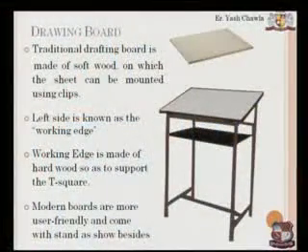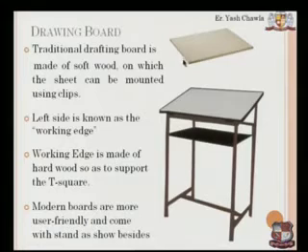That is where the drawing board comes in. I have a drawing board of soft wood, on which I can mount my drawing sheet with clips, just like we mount clips on clothes that we hang on the wires while we keep them for drawing. Well, the speciality of this particular drawing board that we use for engineering drawing is that it has a working edge on the left hand side. Now this working edge has a great deal of importance in engineering drawing.